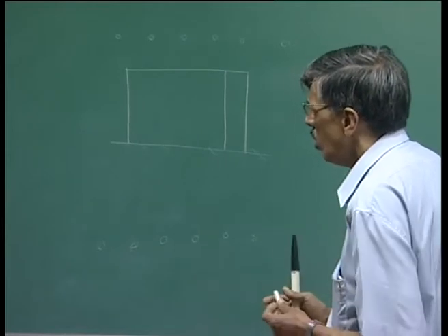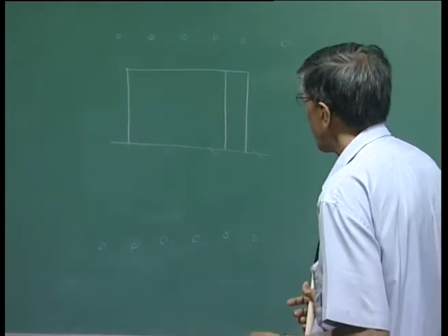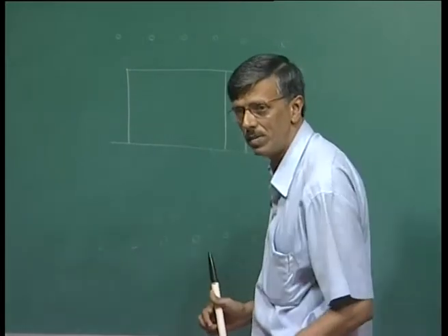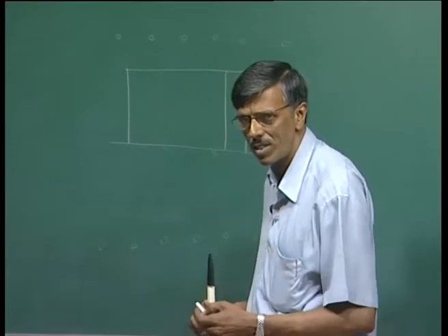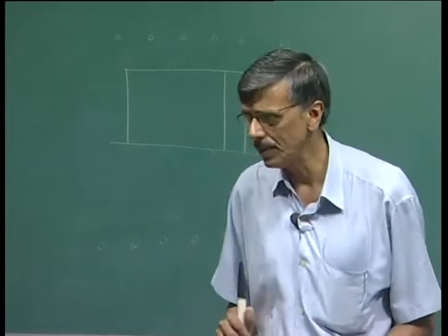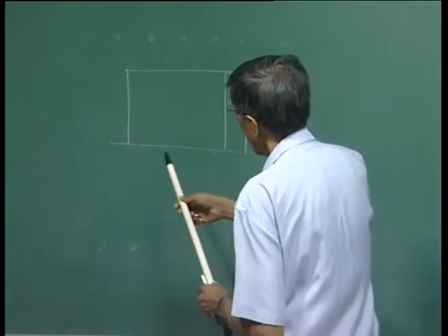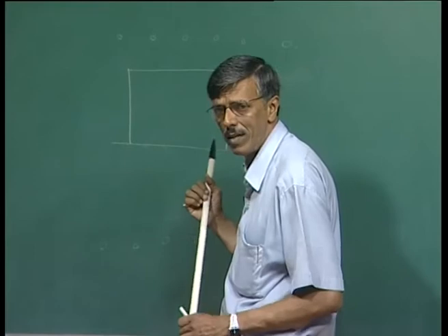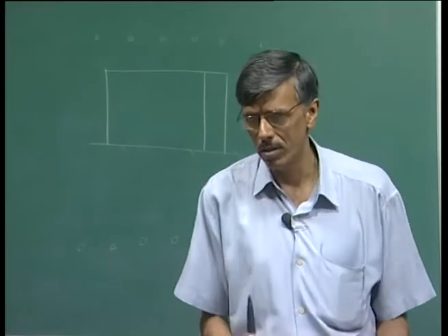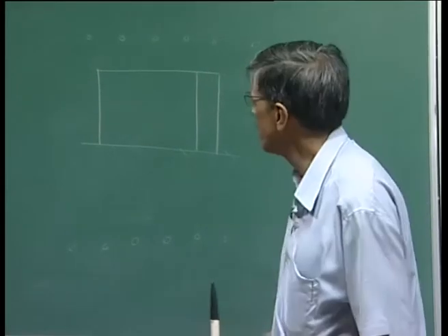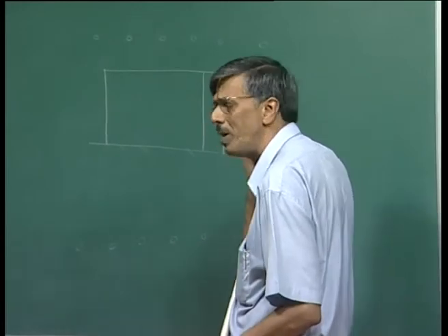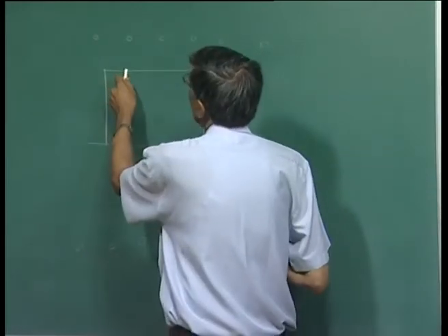So what is really happening in our computational domain: the presence of these two vortex systems will induce a velocity. As they are so far outside the boundary layer forming over the flat plate, if we consider these vortices themselves to be some kind of inviscid irrotational vortex, then the effect of these vortices would be to induce some velocity component.